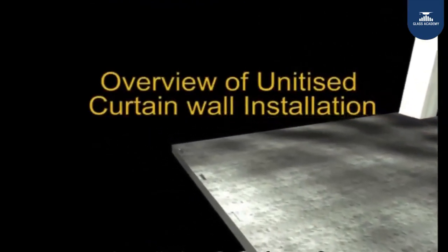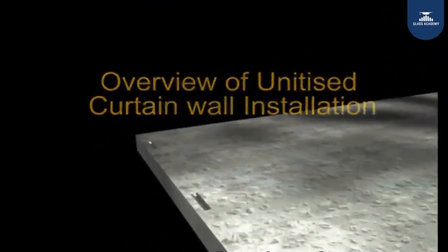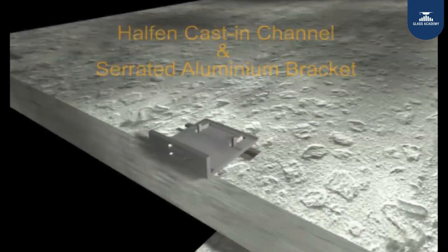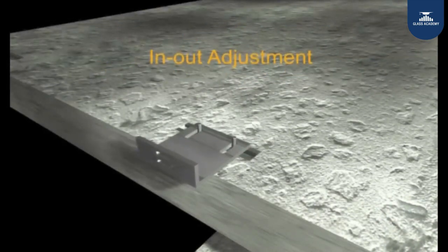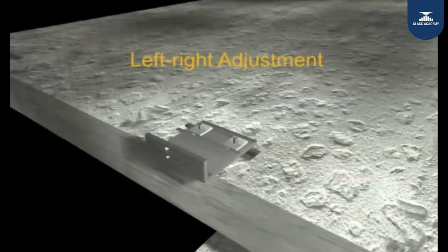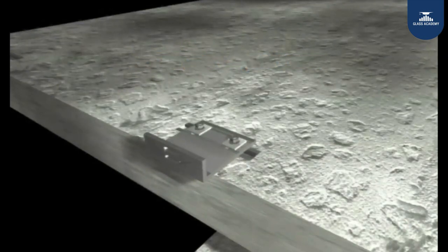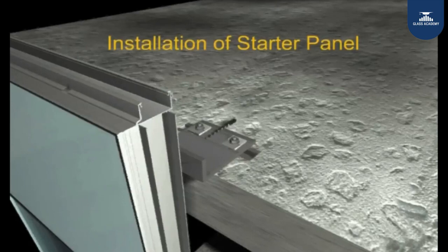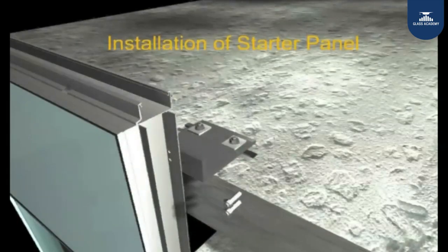So, once again without stopping. You put your channel, you put your T-bolt, then you put your bracket, adjust the bracket for movement, in and out based on the tolerances of the structure, then lock them in position. Your field work is done, that is all you do. Then you wait for the panel from the factory, you attach it with the bolts, 2 bolts, simple, you are done.